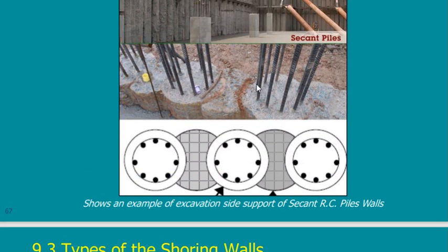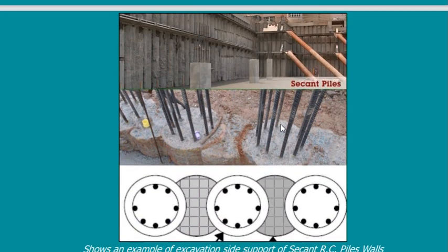So now this is a photo. This is the reinforced concrete pile, and this part is the remaining of the secondary pile that I drilled at the beginning. So now, if I have water inside, how can water pass? It cannot pass through the concrete pile, it cannot pass through the plug, and it cannot pass all around. So this is a watertight section.